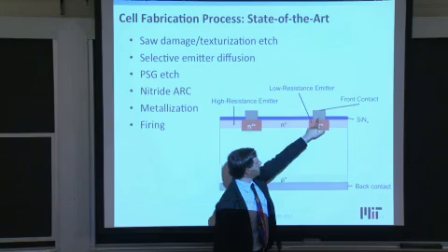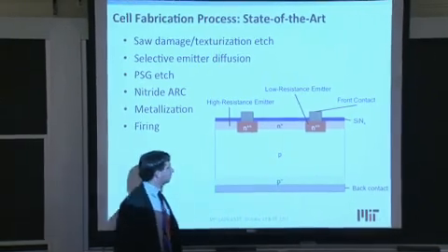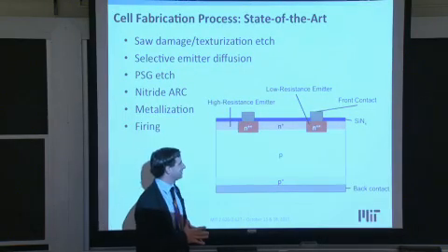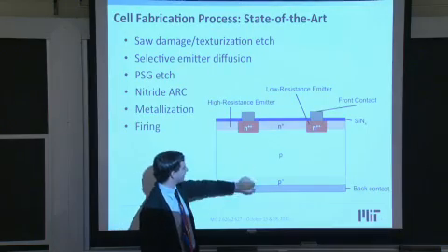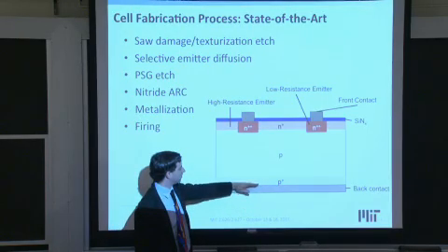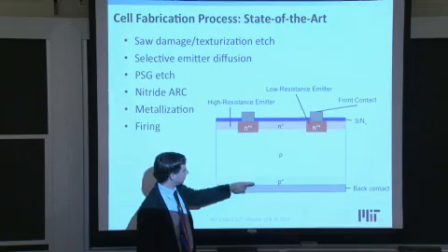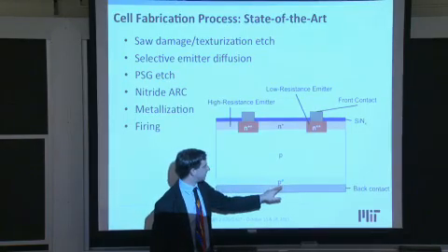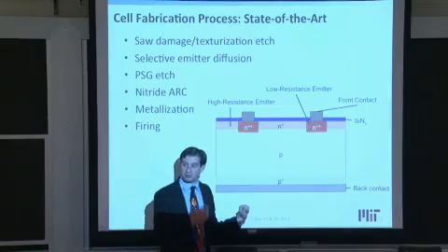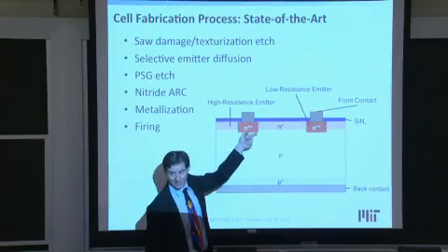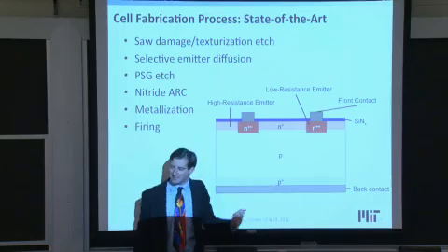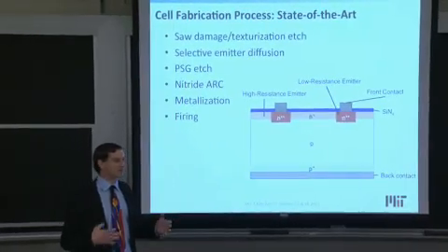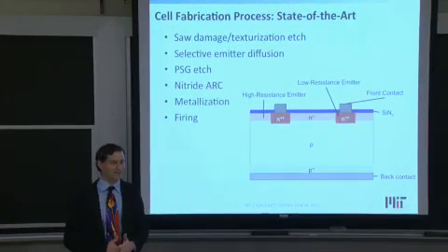The front side, you have to line up, in commercial production, line up with the low resistance portion of the emitter so that you are able to extract the full benefit from the selective emitter design and not shunt your device elsewhere. And on the back contact, this is typically aluminum. Some of the aluminum will indiffuse into the silicon and create a P+ region in the backside here, which is a minority carrier blockade layer. It pushes the electrons away from the back junction and toward the emitter. And so it prevents back surface recombination. So you can see every single little step of the solar cell fabrication. A lot of smart people spend a lot of time thinking about, gee, how do I optimize 2 or 3 things at once? Question up there.